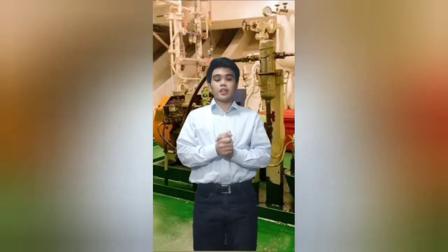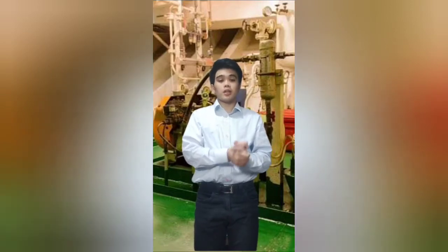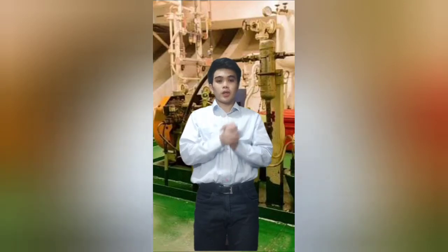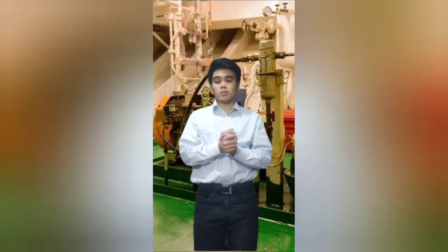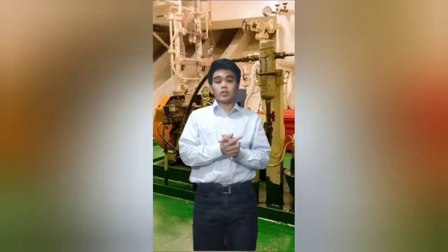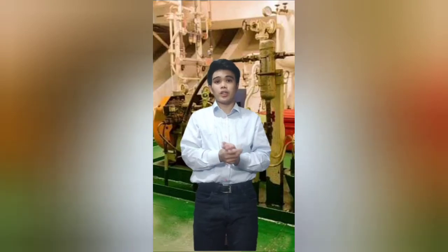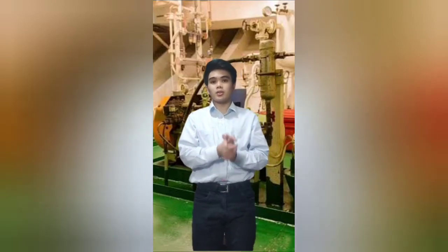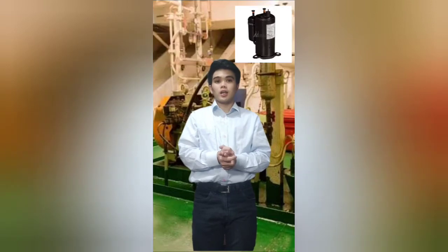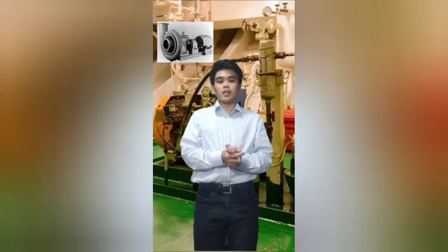So in a compressed air system, there are types of compressors. They are the positive displacement and the dynamic compressor. In positive displacement, it flows with constant flow, while in the dynamic, it works by a constant pressure. What are the compressors included in positive displacement? They are the reciprocating and rotary. And next, in the dynamic, it is the centrifugal and the axial.